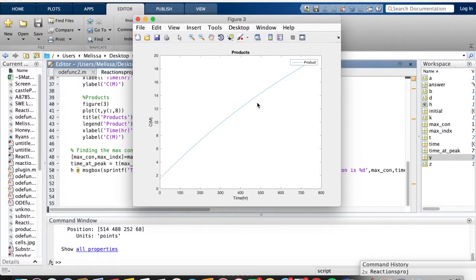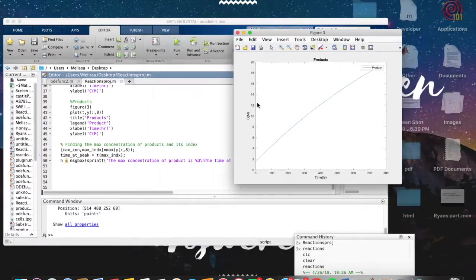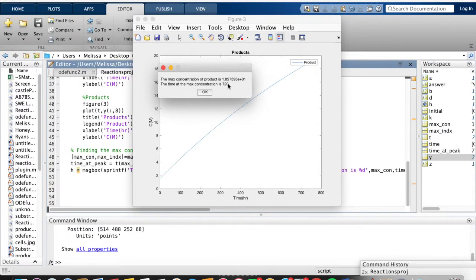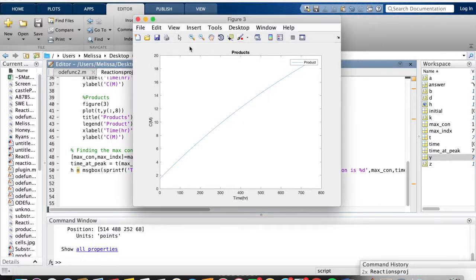And then the next pop-up shows our max concentration, and at the time that is the max. So our concentration is 18.5, that is the max that we got, of methane. And using the assumed theoretical values of biogas composition of 65% methane and 34% carbon dioxide, the concentration of the carbon dioxide will therefore be 9.67 if the biodigester is run for 30 days.